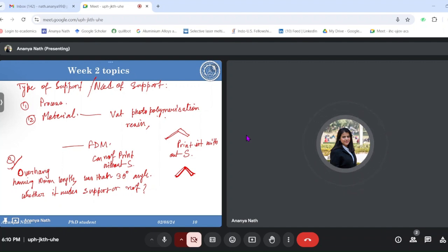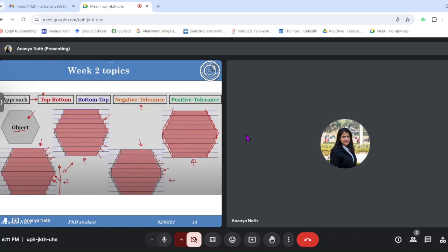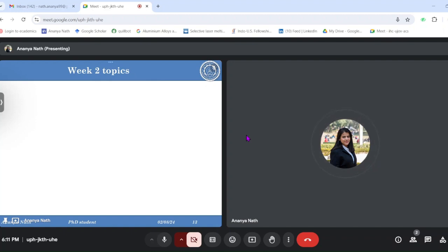The next thing which was studied was the different types of slicing, but before that, the support minimization model, where the multi-objective model was one thing. If you have the support, you can optimize the support, like minimizing the contour. Another thing is, you can also minimize the support by orienting the part.